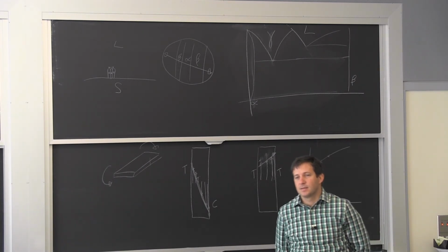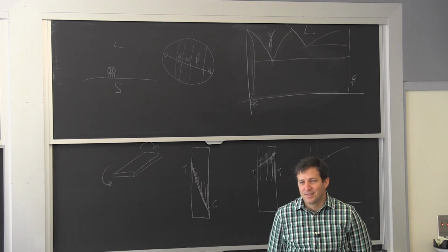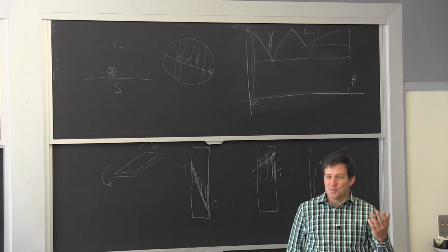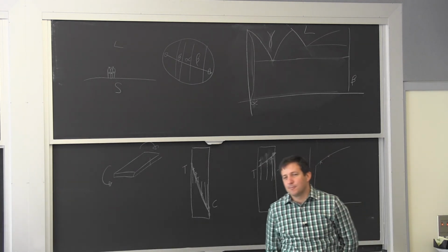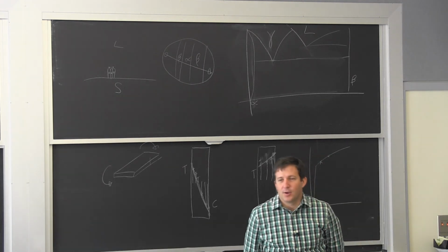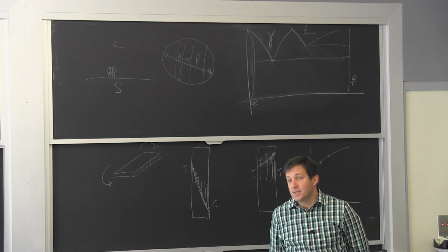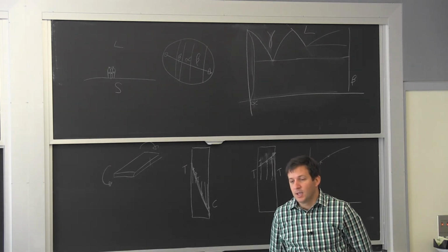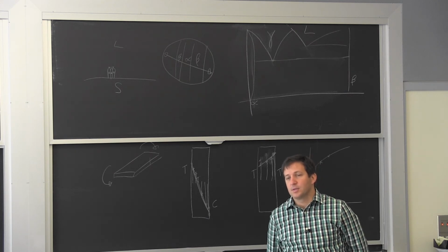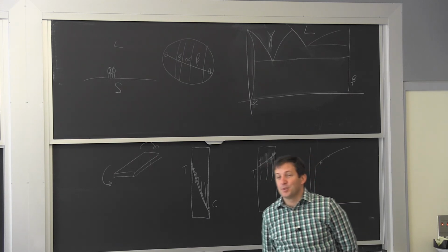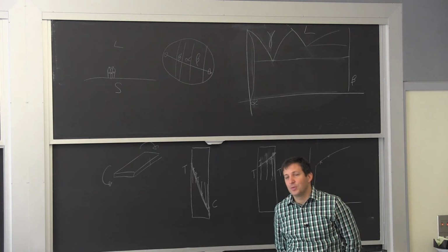Yes? So why do they choose aluminum as the barrier? As opposed to what? You need something that's very resistant, so it tends to be a metal. You need something that's very flexible. At the same time, you want to prevent the flow of oxygen. So metals are very, very good diffusion barriers.